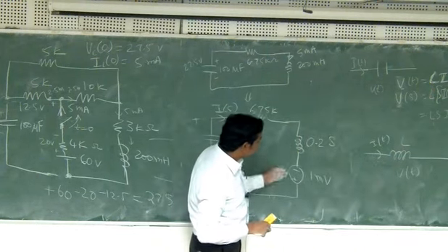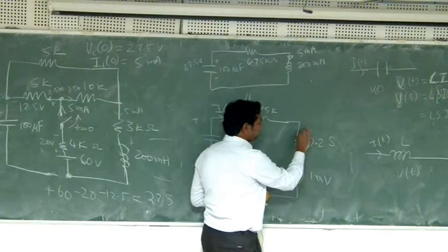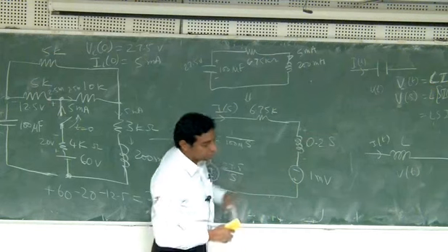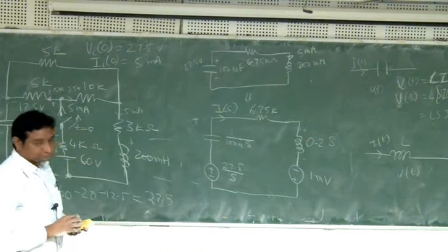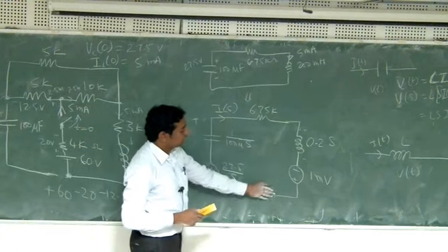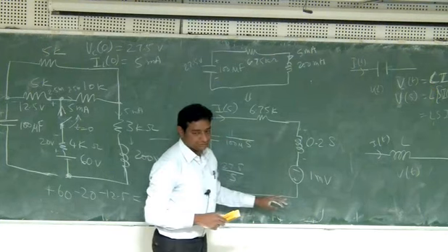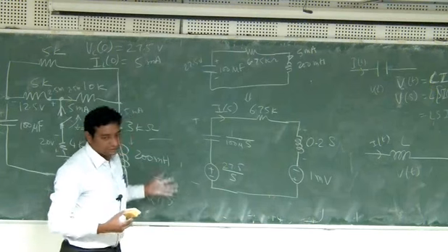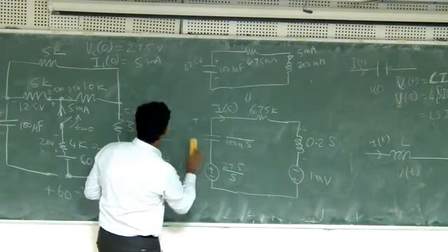So notice that the sign of these two is different. The current is flowing like this, this is high and this is low. So the sign of these two is opposite, so that's why there is a minus sign there. So I think we are all correct. Okay. Now what is the unknown in this? I can find what is Is, and then I can later find the total voltage, because we wanted to know this voltage. Okay. So how do you find Is? Everything else is known. It's just Ohm's law only. So I can write one equation here.